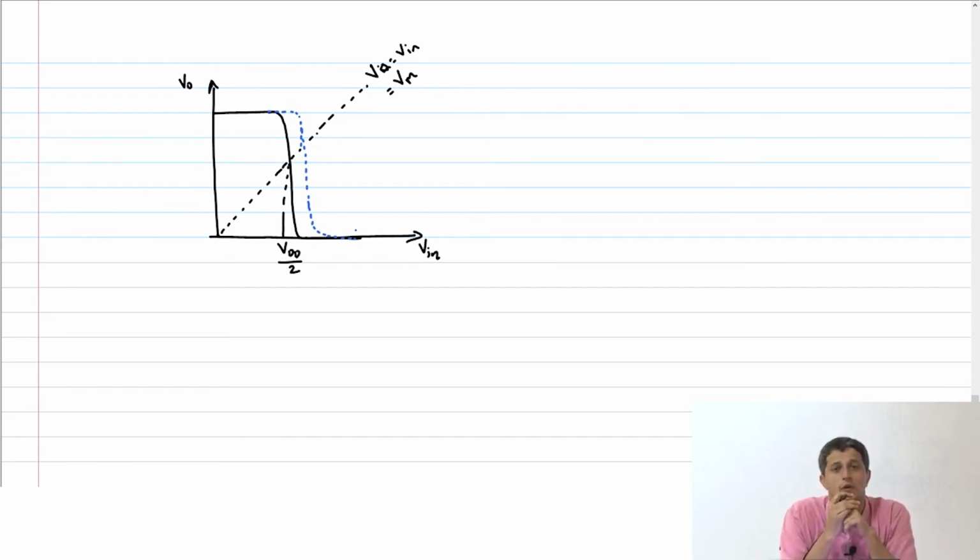Why do you think this should happen? So basically the PMOS gets stronger, that is the width of the PMOS is going up. That means the PMOS current is stronger for the same Vin as I would have had for the earlier case, right? So if that is the case, then where should Vout land up?